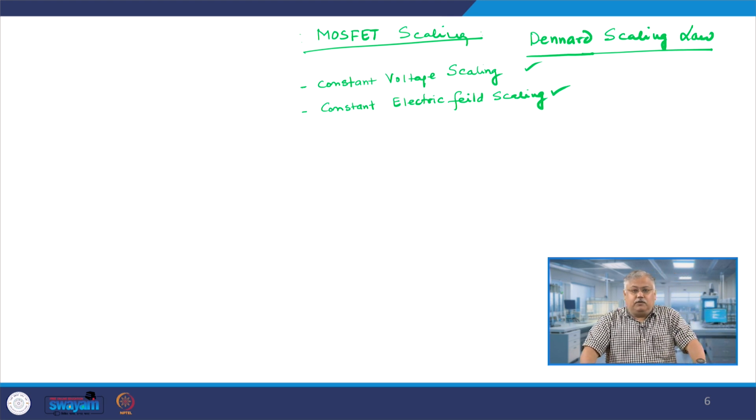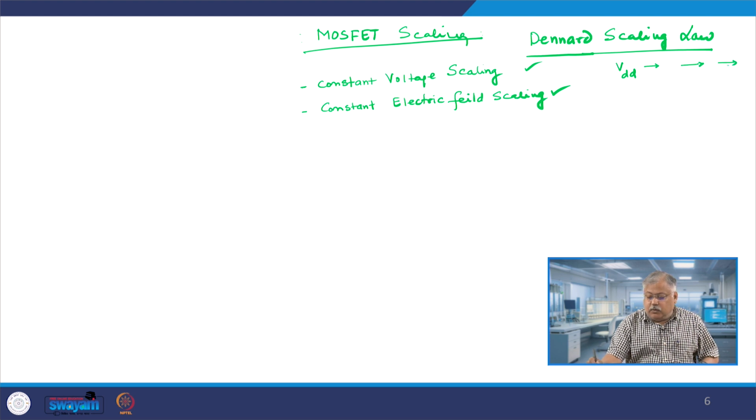I will explain each one of them individually. Constant voltage scaling means that you are only scaling down the voltage, which means that if you have some voltage VDD, as you progress in technology you scale this VDD down by certain factors, right. You scale it down, right.